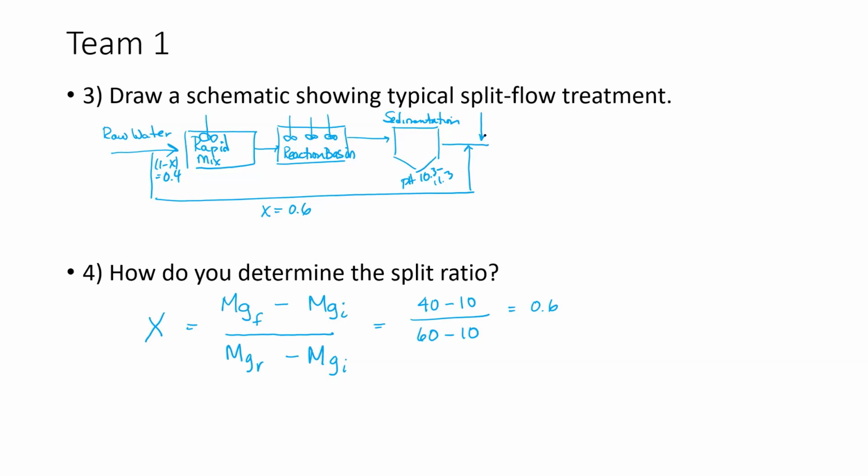We can either reduce the pH by mixing, and that works in some cases depending on the alkalinity, depends on the ratio of bypass, or we use what is referred to as recarbonation. So here we're adding CO2. So we add CO2 gas that reacts with water to produce carbonic acid, which results in a pH reduction.